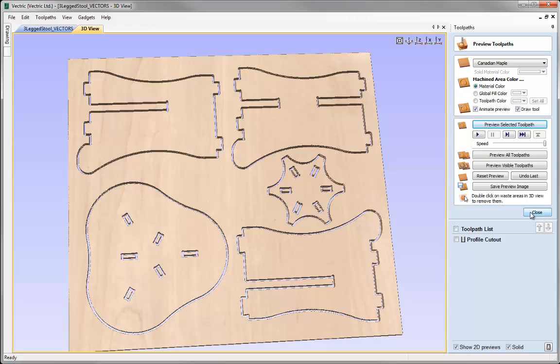In addition, there's some other things I'd like to do here. For instance, as we cut these areas out here, I'm going to end up with some very small bits of material. Even if I have a vacuum hold down, it may not be enough to hold parts down as small as this. I don't want to really put tabs in there because I'm going to have to then cut those out manually and clean those areas up.